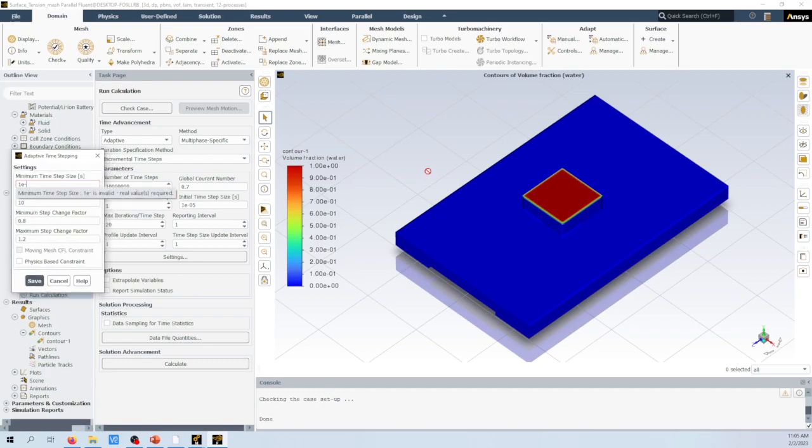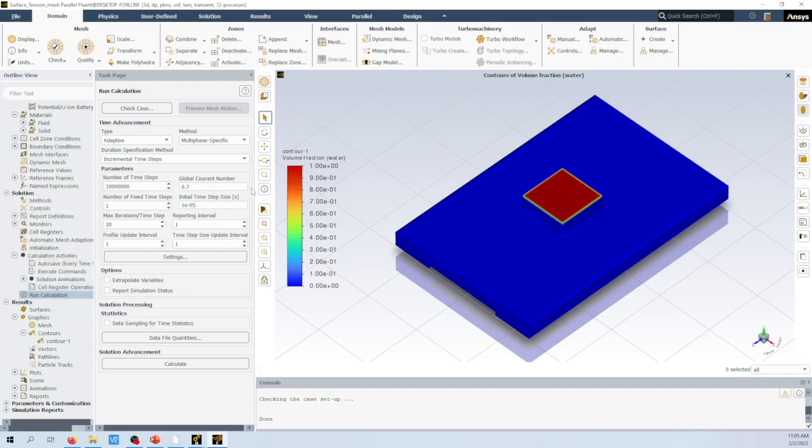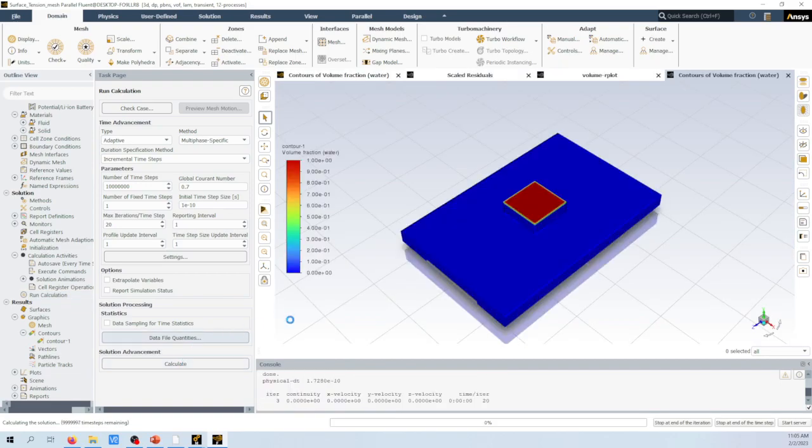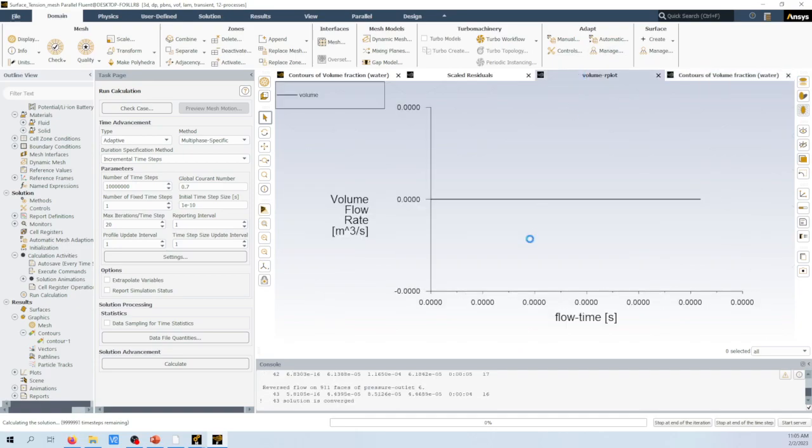Now our minimum time step size needs to go down, way down, because our geometry is small, way small. So now that we have a smaller initial time step, if you go any higher than 1e negative, honestly, yeah, 1e negative 5, your solution will diverge immediately. So it's no good. Now that we have all of our parameters, let's see the solution. Now you can see it flashing here, taking the snapshots. That would be a picture every time if we had done it.